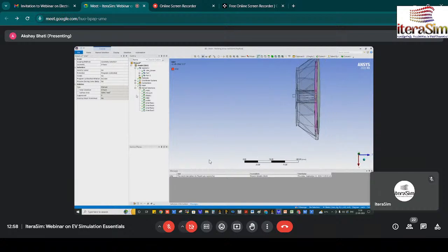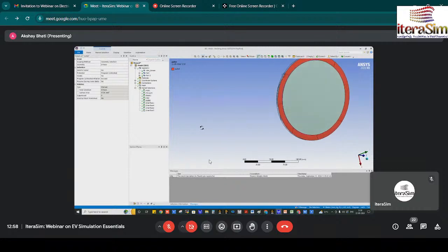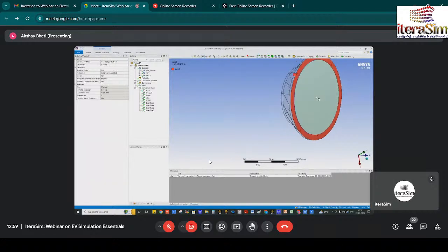And at the outlet here I gave a smaller outlet because I want to flow the air at the casing of the motor. So I gave a support structure here, because I don't want any flow in that domain. If you check the motor, there is an air casing at the periphery of the motor, there are fins. So I want to flow the air on that periphery.